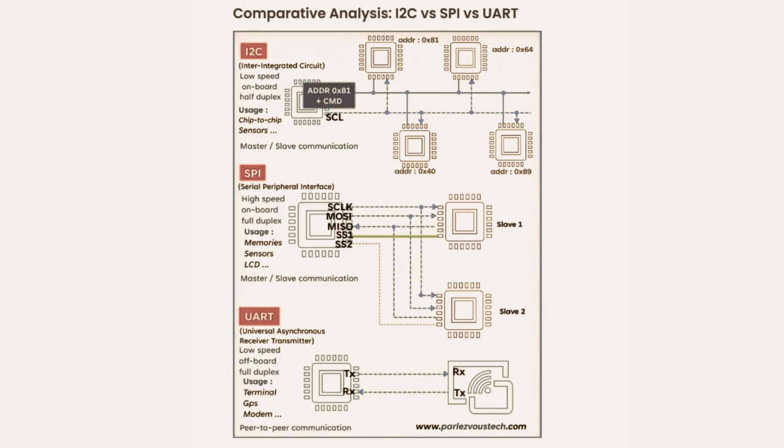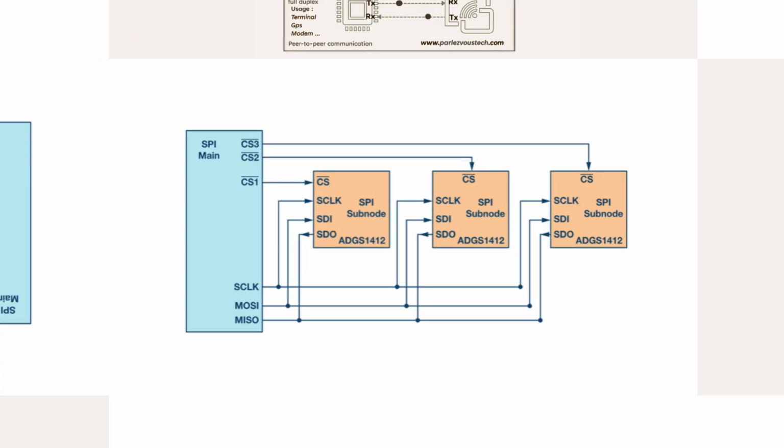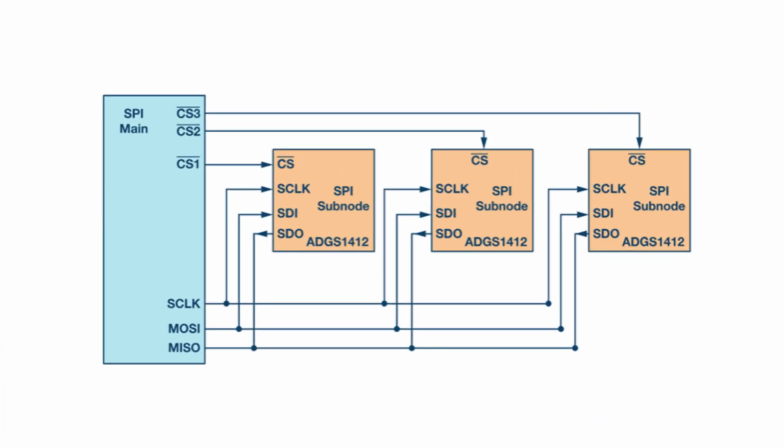Now, any data sent on MOSI is meant for slave #2, and only slave #2 is allowed to put data onto the shared MISO line. All other slaves, slave #1, slave #3, etc., remain inactive because their CS lines are still HIGH. The master communicates with slave #2. When finished, the master pulls slave #2's CS line back HIGH. Slave #2 goes back to sleep and disables its MISO output.